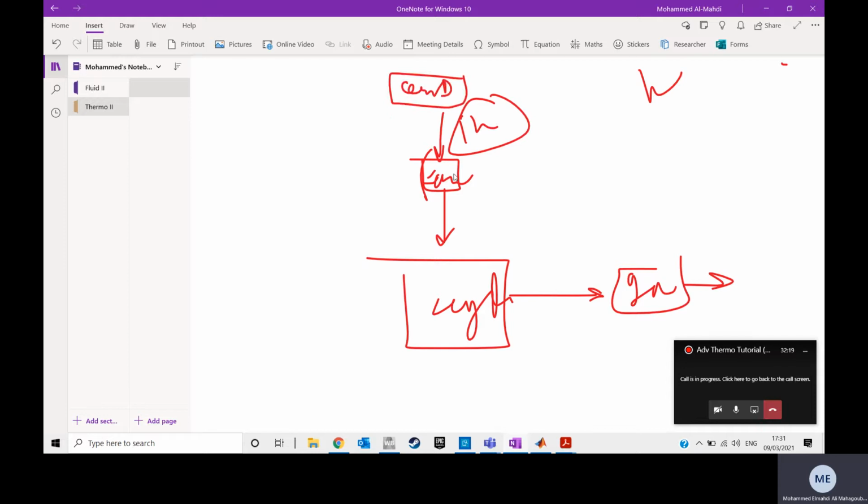It happens here, and here is where the combustion losses happen. So I want to find this heat input. This one is the one that will tell me what's the m dot of the coal. Because if I used m dot of the coal here after the losses are happening, then I'm going to end up with an amount of coal that is less than what I'm supposed to have.